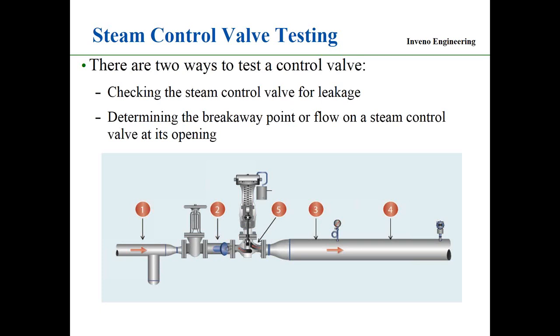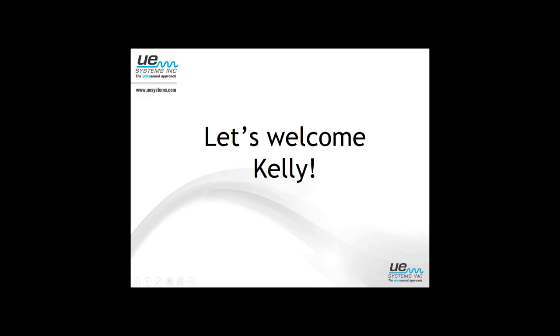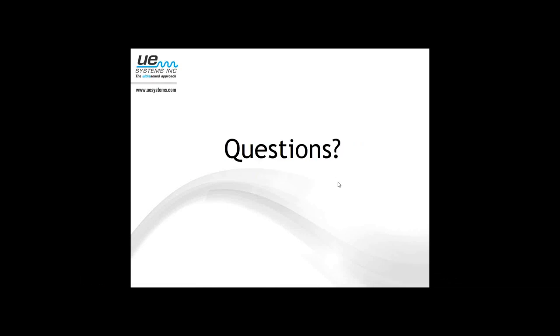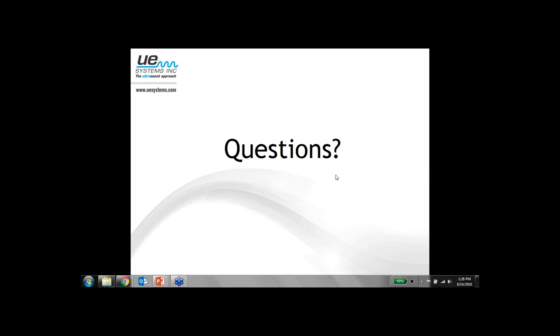And then this other person asks, if valves and steam traps are surrounded by insulation, how do you test them with ultrasound? Again, if insulation is a factor, if it's permanent insulation, make a test port where the stethoscope module will go through and make contact with the pipe. Once the test is done, plug that port, which gives you access from that day forward. You go up, look for the plug in the insulation, remove it, and then the probe can go in, which is done all the time.